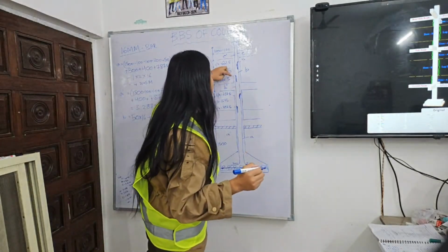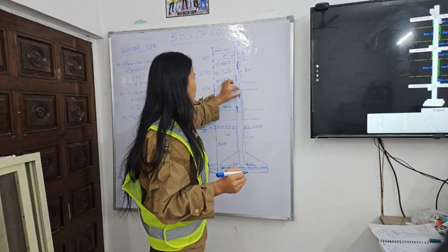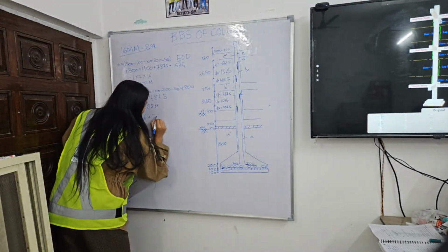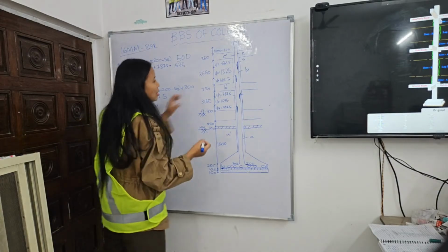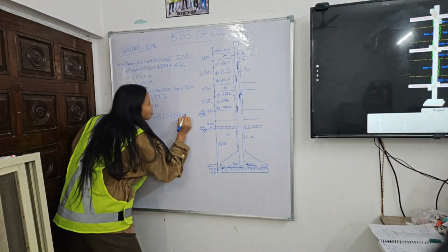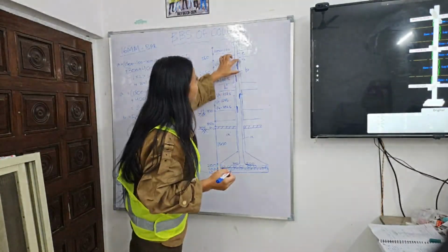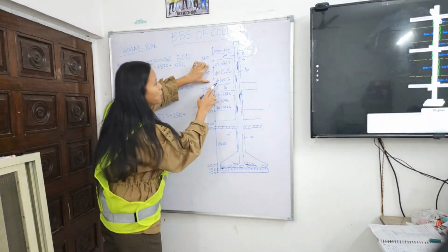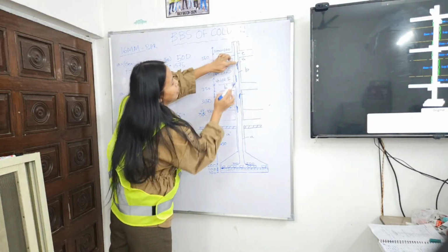So from here we have slab beam. First we are going to add this L by 4, from here till here is L by 4, 787, plus the slab beam we have is 350. Plus now till this much, from here till L by 4. So till this much we are adding L by 4 plus L by 2. See, L by 4 will be this much and L by 2 will be this much.